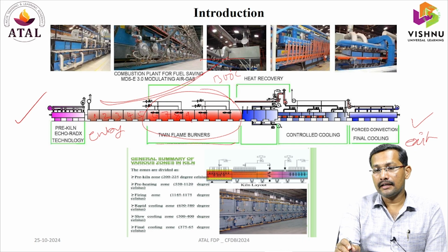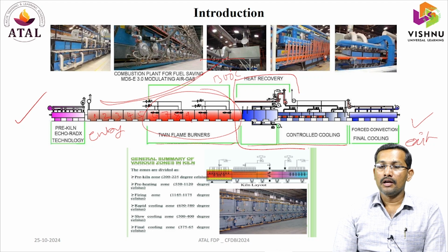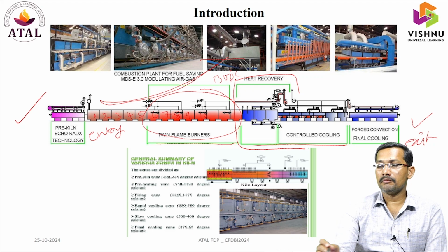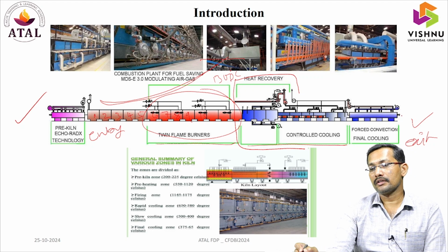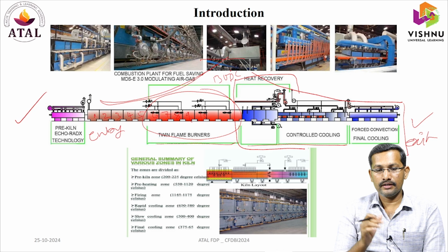The next one is the heat recovery part. Here there is one concept, heat recovery. We are extracting the waste heat, that is, some hot air that we are producing. The next step is slowly cooling the tiles. After bringing them to 1300 degrees centigrade, by the end, when the tile comes outside of the kiln, we need to cool it slowly. All of a sudden, we should not cool. We decrease its temperature slowly down to room temperature, so that the tile establishes the required strength.